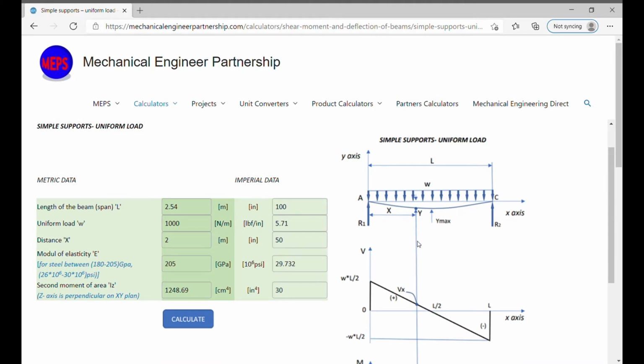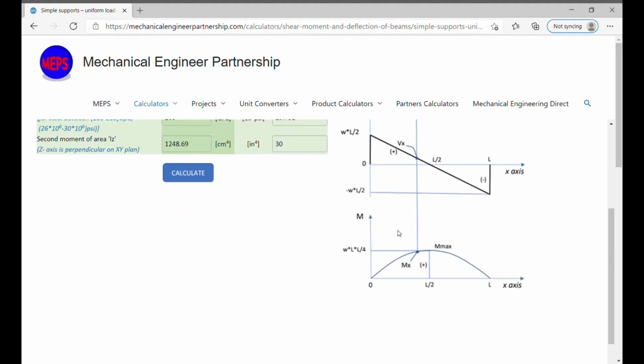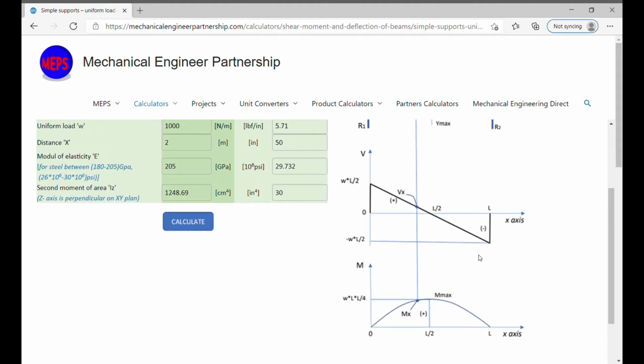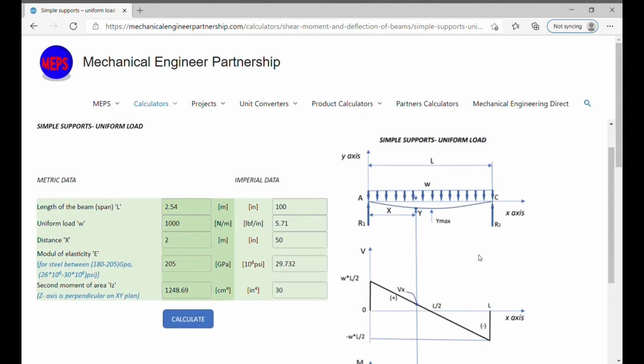The shear force is obtained by summing the forces on the isolated section. The bending moment is the sum of the moments of the forces to the left of the section taken about an axis through the isolated section. The sign conventions used for bending moment and shear forces are clockwise for positive moments and counterclockwise for negative moments. Positive shear forces are in the same direction as the y-axis in the figure, and negative shear forces have the opposite orientation.